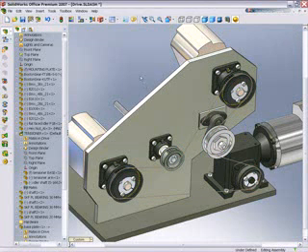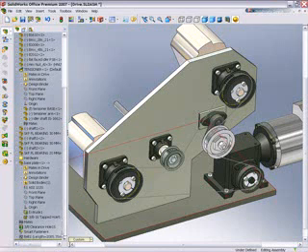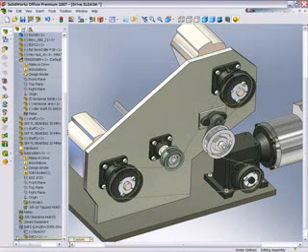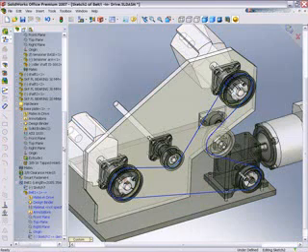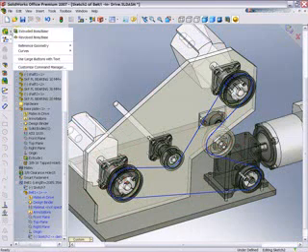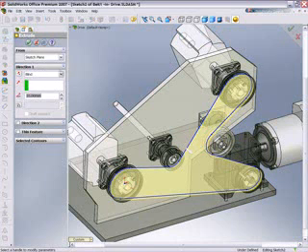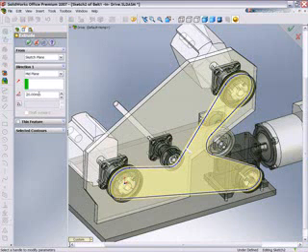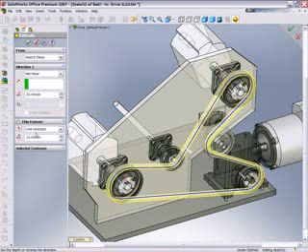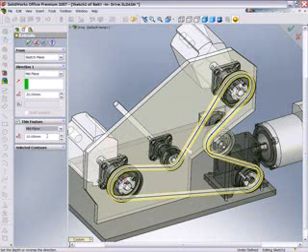The belt location plane controls axial position of the belt relative to the pulley. Users can also input a belt thickness. In addition, a dynamic tally is always kept of the current belt length. The belt can be saved as a part. Further detailing of the belt, such as the creation of the cross-section of the belt, can occur in Edit Part or in regular part mode.